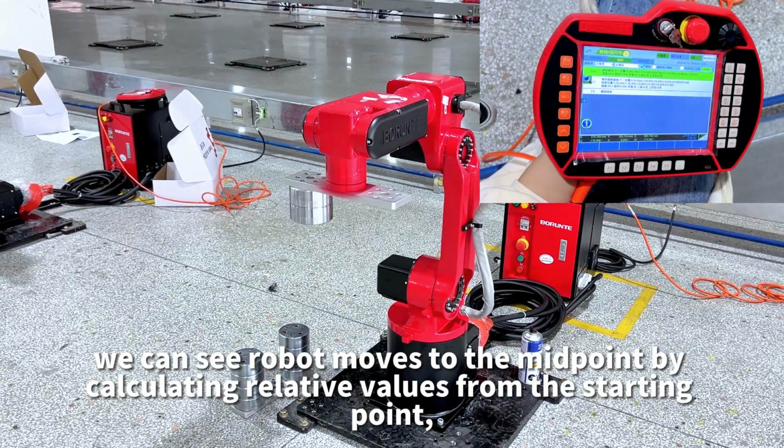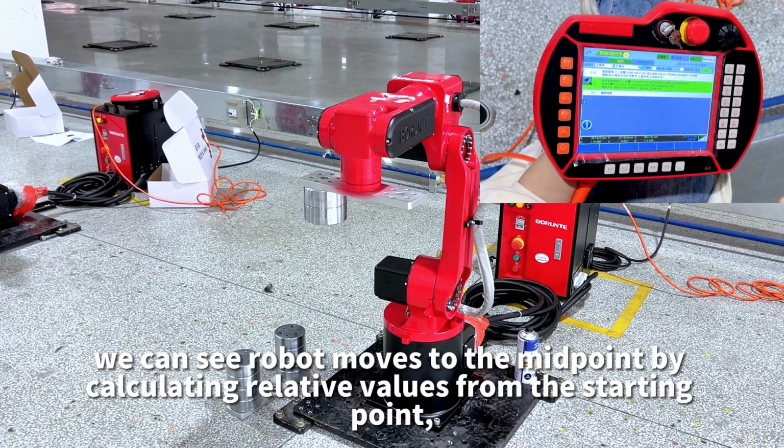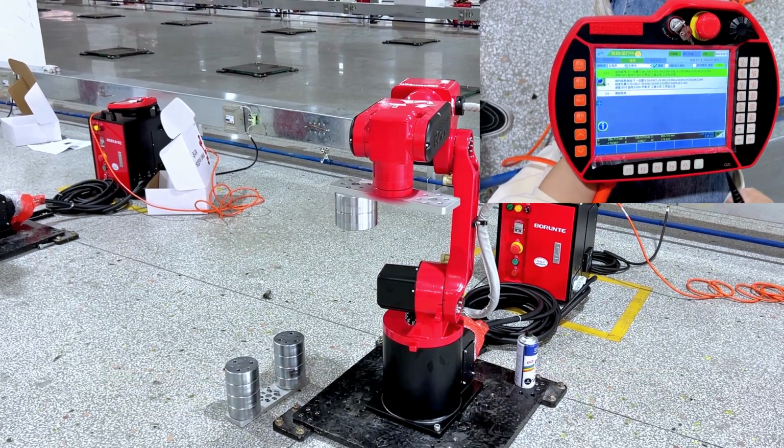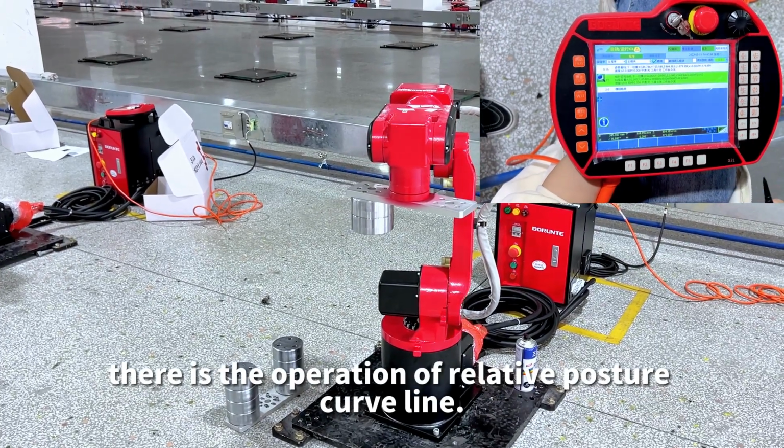We can see the robot moves to the midpoint by calculating relative values from the starting point. Then calculate the relative value data from the midpoint and move it to the endpoint. That is the operation of relative posture curve line.